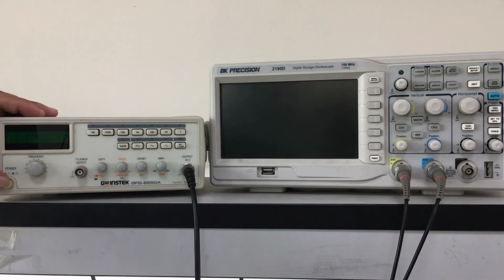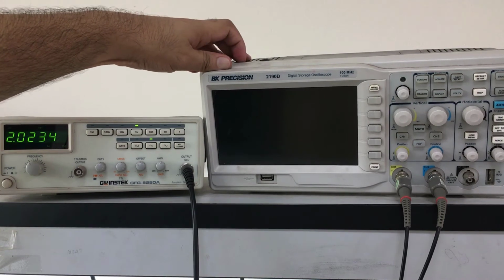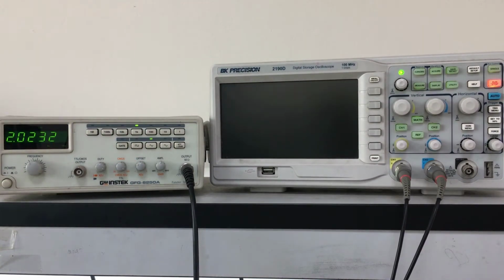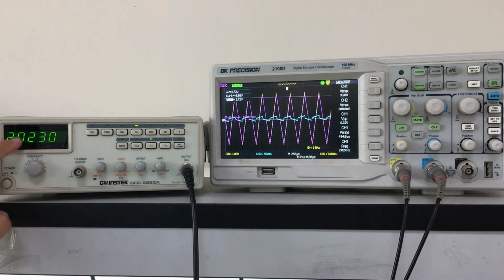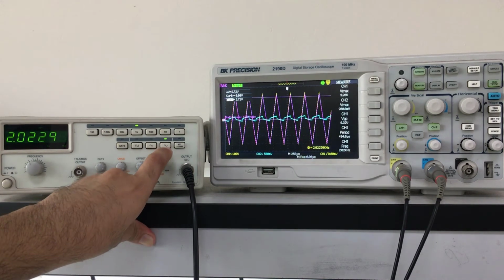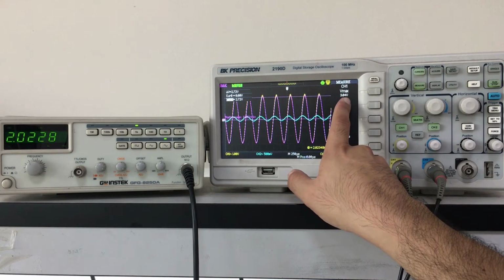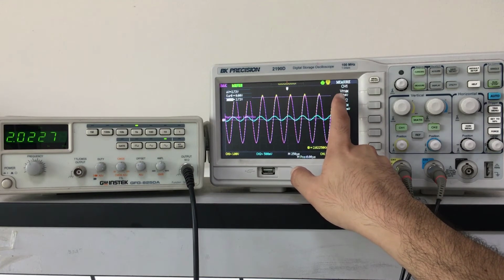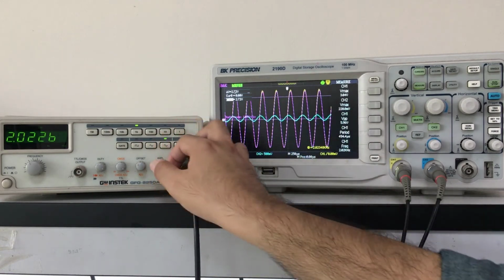So now we turn on the function generator by pressing the power button, and turn on the oscilloscope by pressing the power button located at the top. So 2 kilohertz is the starting frequency for the function generator, so we don't need to change the frequency. However, the default starting waveform is triangular. We change it to sinusoid. We see that the amplitude is 3.04 volt, which is required at channel 1, which is connected to node A. So if it is not 3.04 volt, we would have to adjust using the amplitude.